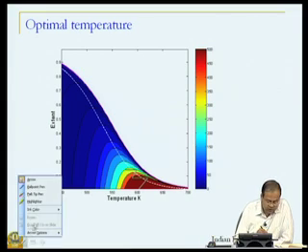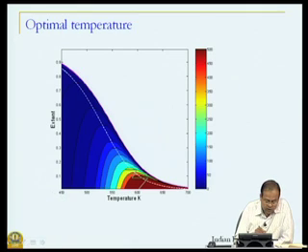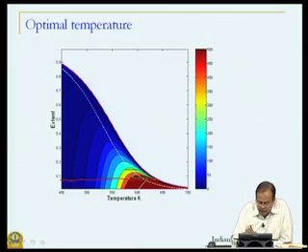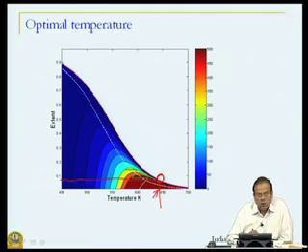So, let us say that given this composition of the inlet, my temperature is this particular value, T10. Okay. So, what will happen if my entry temperature conditions are such that the reaction is at equilibrium, because I am putting this point on contour of rate equal to 0.